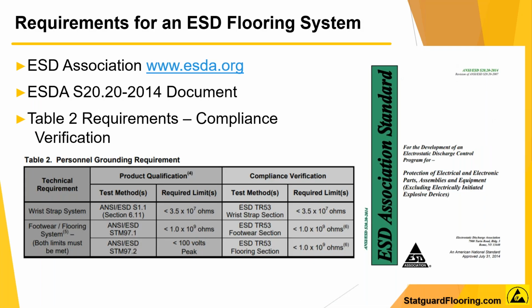The requirements for an ESD system are covered under the S20.20-2014 standard. While there are several standards that can apply to ESD control flooring, depending on the application, by far the most used is the ANSI ESD S20.20 standard from the ESD Association. This standard was last revised in 2014, at which time significant updates were made, most notably to the qualification method.